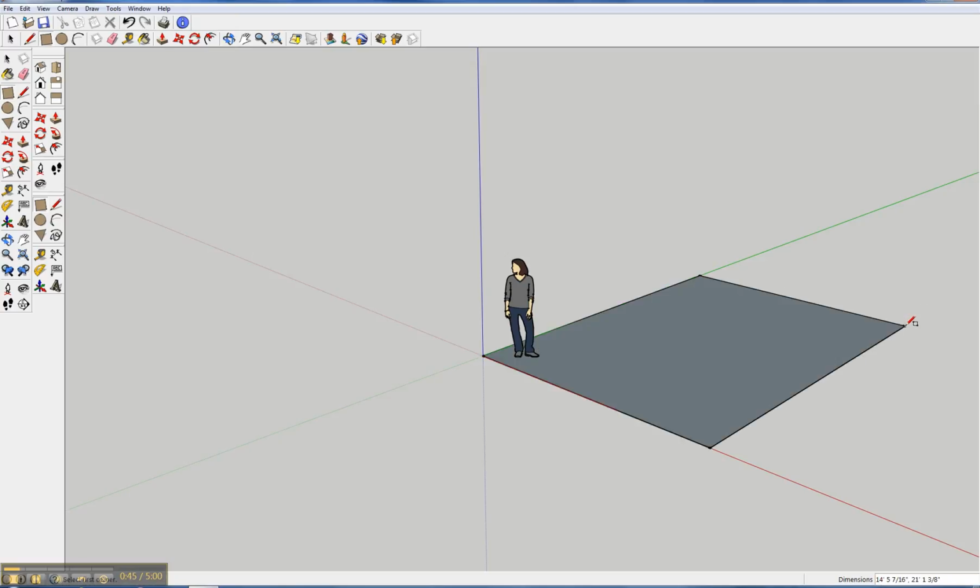I'm going to make this rectangle 14 feet, and when you do the foot symbol, it needs to be that one little dash next to the 4. You need to add the comma and then type in the next number. I'm going to type in 20 feet. And notice all my symbols and all my numbers are accurately typed in the dimension area. When you are done, you hit enter. Notice how the square adjusted to my measurement.